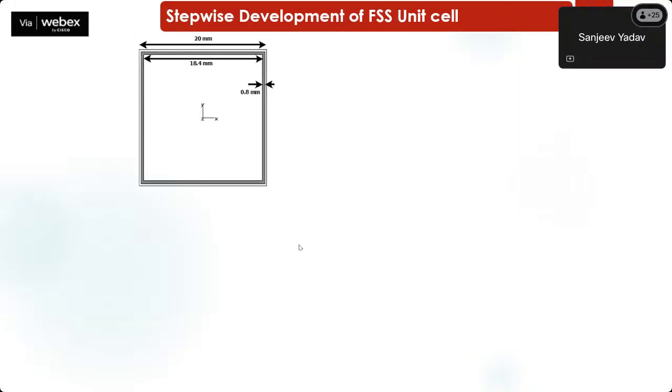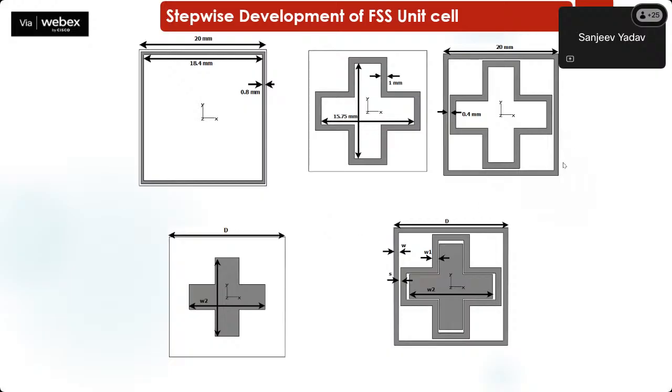For getting multiple resonances, you can adjust the spacing between adjacent elements so that the small bands combine, and you will get a wide band. Like in this structure, if I want to get a wide band, I can put other ring structures very near, with very close spacing, so that one resonates at 1.1, another at 1.2, a third at 1.3.